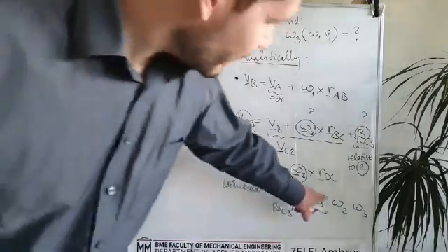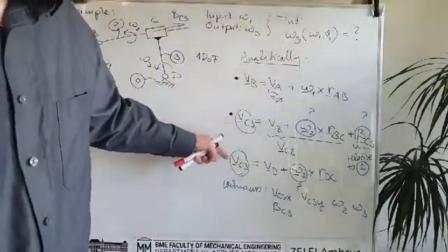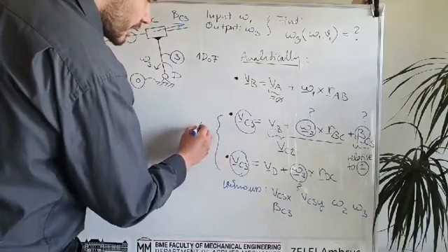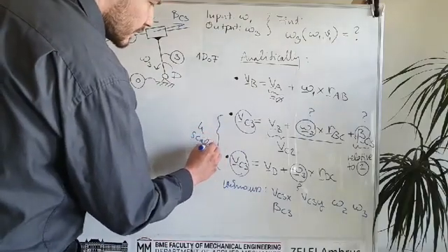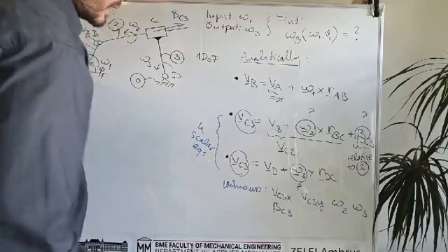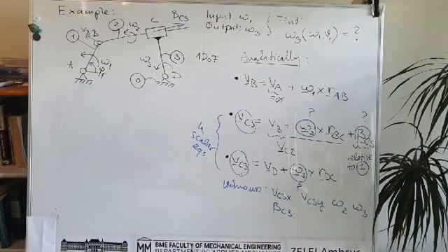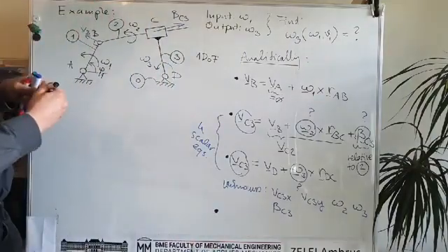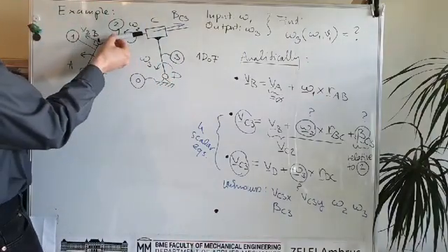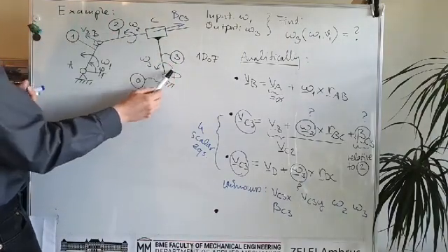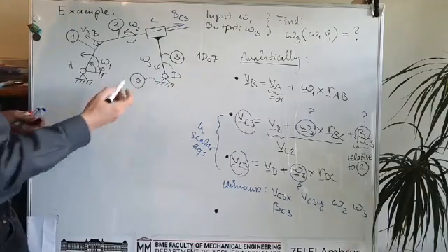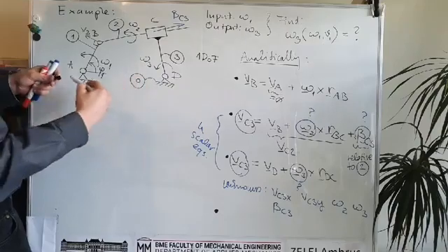So we have 5 unknowns and 2 times 2 equations, which is basically 4 scalar equations. So we have one more equation, and the additional information is that this rod is always perpendicular to this one. Therefore, we can say that the two angular velocities are always the same.